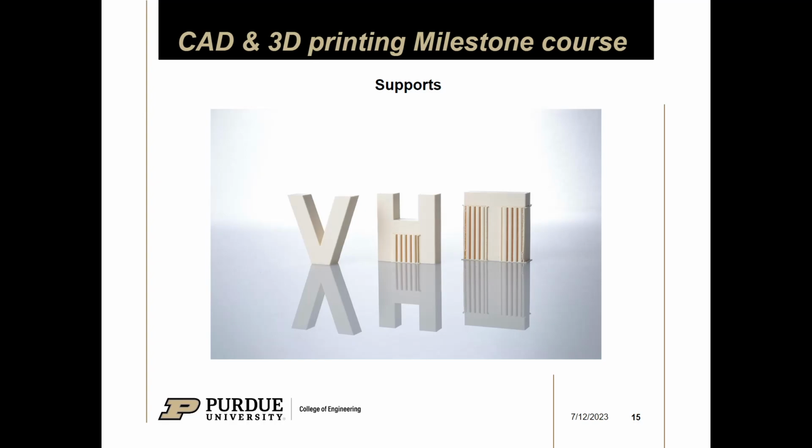Generally, when you're 3D printing, you want to try to avoid designing parts that need supports unless you really have to. But I'll go into how to optimize that later in the lecture. Here you could just lay them down and then you wouldn't need the support material. Yeah, you could do that too. Print orientation is important. An SLS printer doesn't need supports because it uses the powder as supports. But I'm mostly talking about FDM 3D printing today.